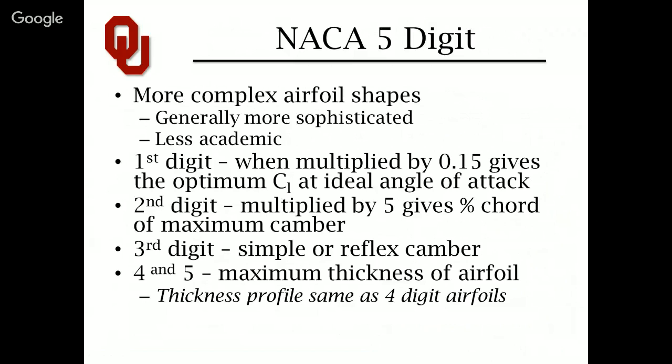Aside from the fact that they're good profiles, they have appreciably low drag. They basically represent an advancement in airfoil technology beyond NACA 4-digit series. The fact you can dial an optimal CL just by changing one number shows how much thought they've put into just the empirical and other mathematics inherent to the 5-digit series of airfoils. So if you see first digit is 1, you know that airfoil will have an optimal CL of 0.15. 2 will be 0.3, 3 is 0.45, etc.